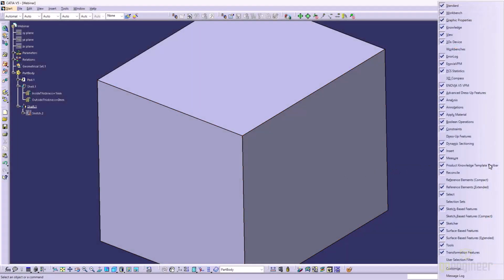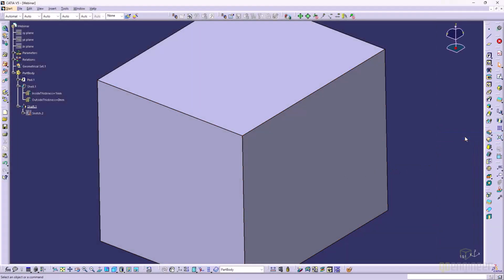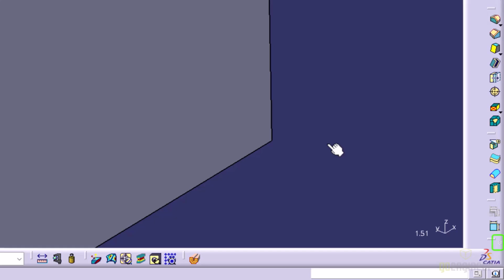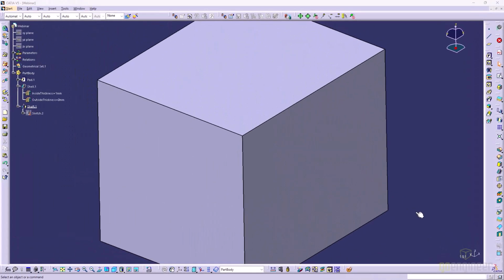Toolbars can also be activated by right-clicking in CATIA's gray perimeter to showcase the contextual active toolbar menu. Toolbars can dock with items that are outside of the display, indicated by a double caret symbol on the toolbar. If this double caret symbol is in your interface, you have features or entire toolbars that are not currently visible. To resolve this, you must move the toolbar to your preferred location for all feature visibility. Do this by clicking and dragging the toolbar's embossed rectangle to a location where you can see all the features, and continue this process until you no longer have the double caret symbol present.